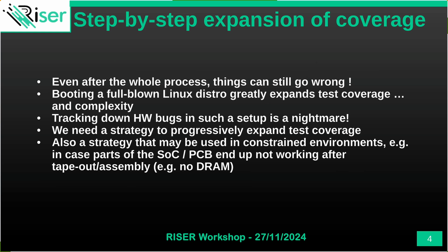For example, one of the common things that can go wrong is DRAM, where you have your chip ready, and suddenly you don't have any memory to play with. Before you go back to the drawing board, before you say we cannot do anything about it, you still need to test whatever is possible, any other peripheral, whatever test you can do to at least make sure which parts of the system are working properly before you may find other bugs as well.